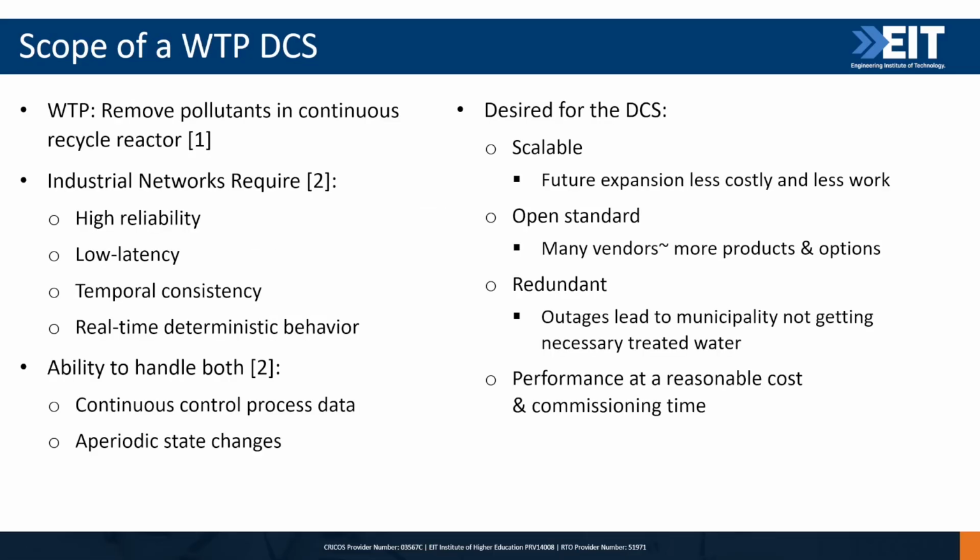The goal of a wastewater treatment plant is the removal of pollutants in a continuous recycle reactor while maintaining the pollution concentrations at the set point optimized by the SCADA system. For control loop stability, response times are generally shorter than the sampling times, and they require predictable transmission, minimal latency, and jitter. The control and safety data require high reliability and strict real-time constraints, with diagnostic and historic data placing less emphasis on reliability and real-time constraints.